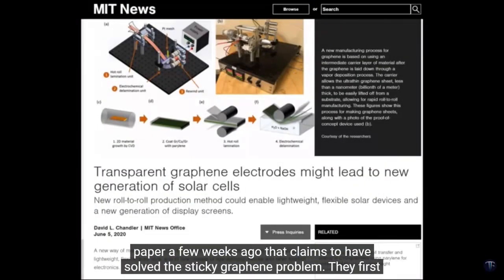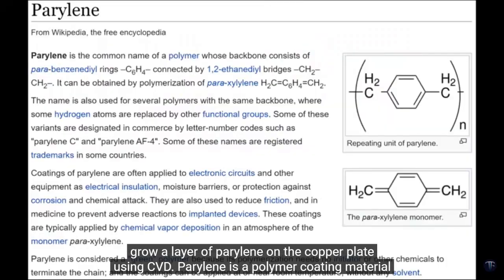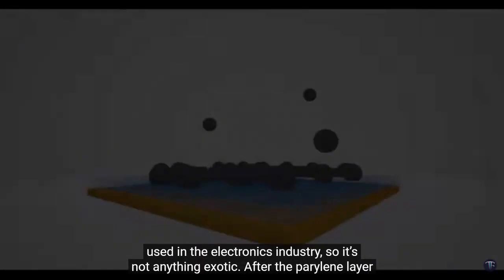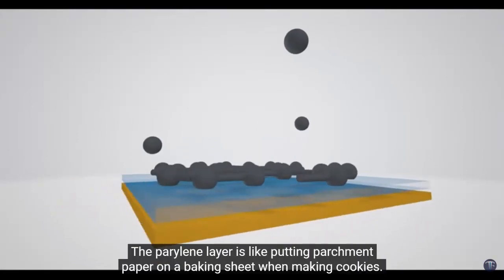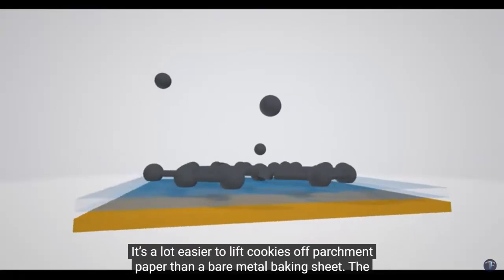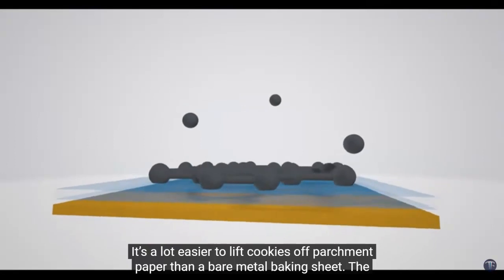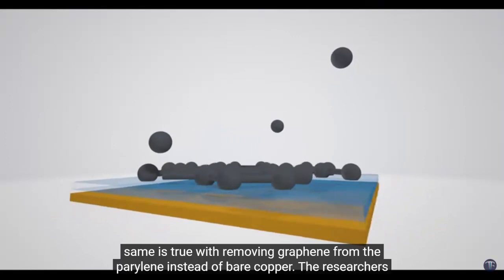They first grow a layer of parylene on the copper plate using CVD. Parylene is a polymer coating used in the electronics industry, so it's not anything exotic. After the parylene layer is grown, then the graphene layer is grown on top of it. The parylene layer is like putting parchment paper on a baking sheet when making cookies. It's a lot easier to lift cookies off the parchment paper than a bare metal baking sheet. The same is true with removing graphene from the parylene instead of bare copper. The researchers claim that the graphene can be lifted off the parylene easily and without damage.